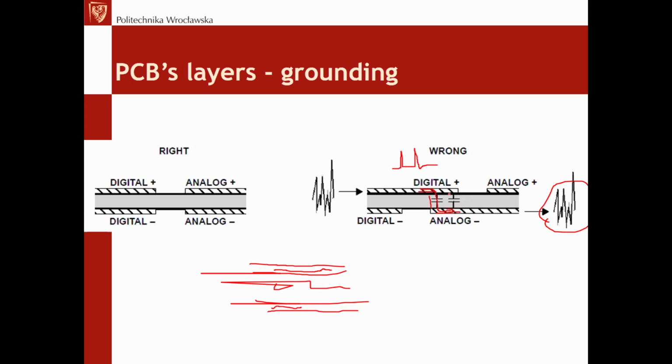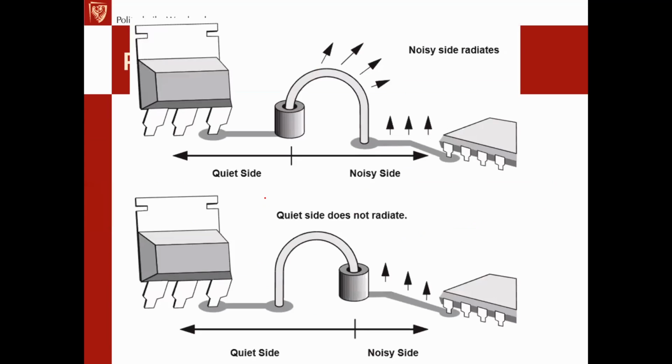So this stray capacitance, of course, is quite nice if we have the ground planes and the signals are then decoupled to these ground planes. But the planes of the digital world or high frequency board or high current switching world shouldn't overlap, even through the PCB, because we may have such a problem.